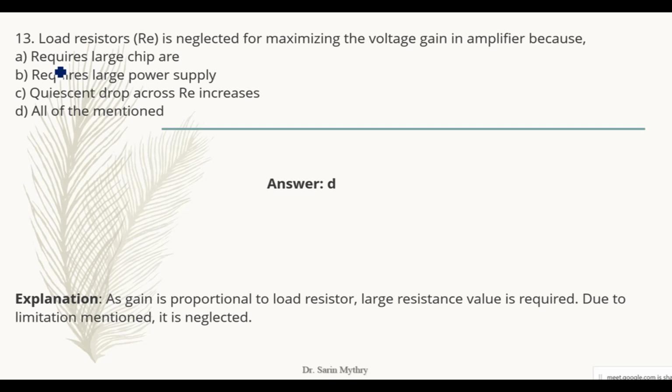integrated circuit. We know that presently the integrated circuit size is very small. It's 7 nanometer. Most of the mobile phones nowadays are going to come up with 5 nanometer. You can imagine how small an integrated circuit is. It becomes very difficult to design the layout or fabricate a resistor over there. So the physical resistors have been removed, and instead of physical resistors they are using pseudo resistors.